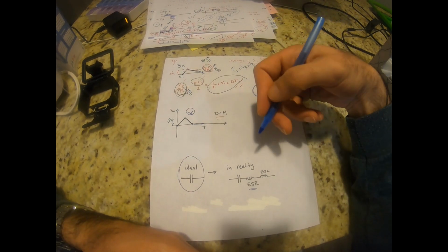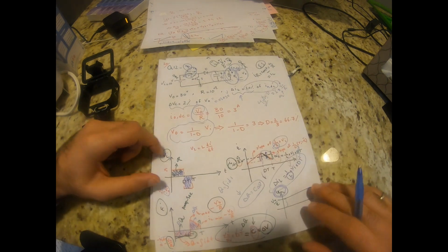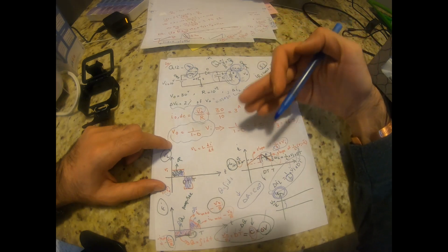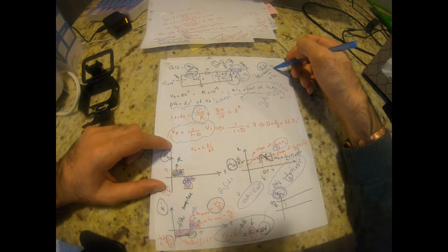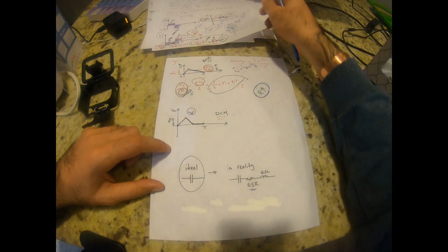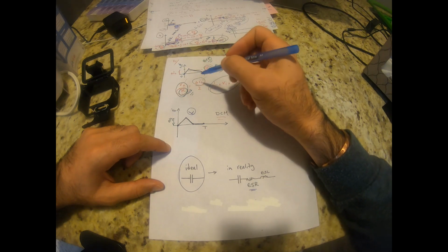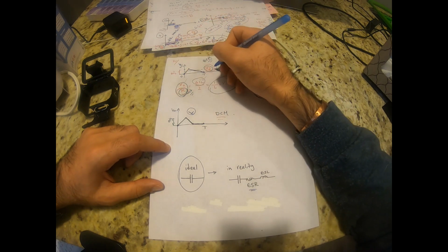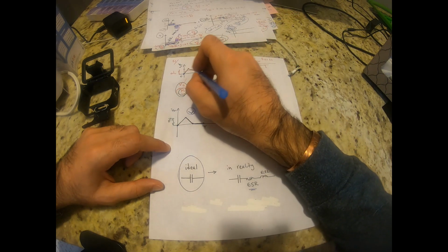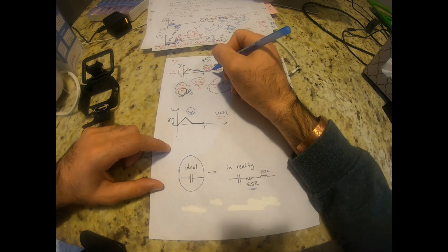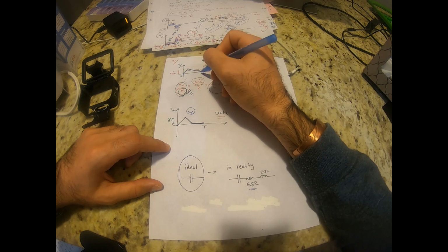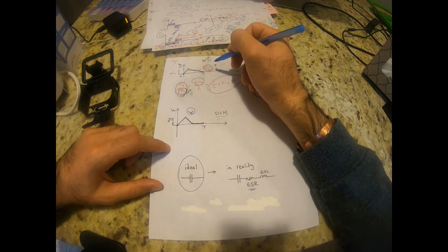Now, once you increase your resistance, the value of current goes down, right? IO is equal to VO over R. As you increase the resistance, IO goes down, right? And the same for IL. And the average of IL is always equal to IR. So the average is always VO over R. At the same time, the average of a triangle is delta IL divided by 2.